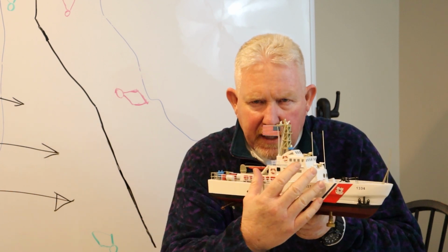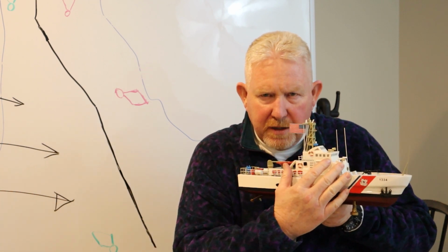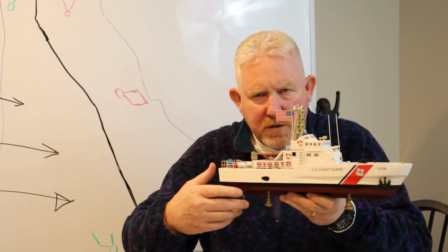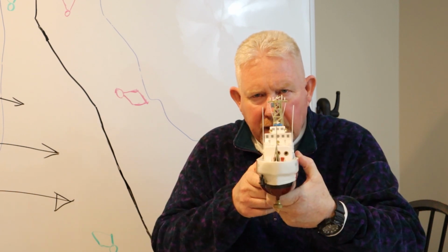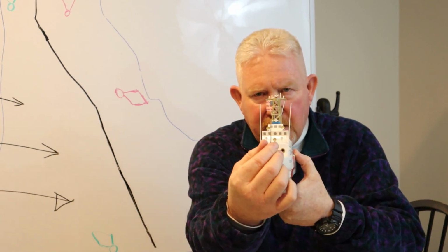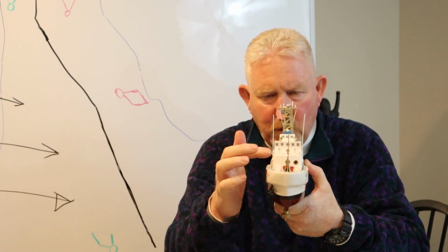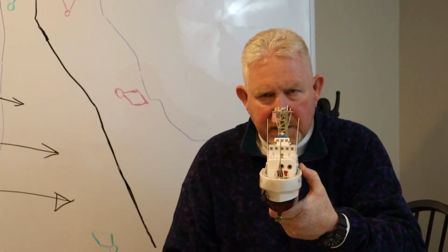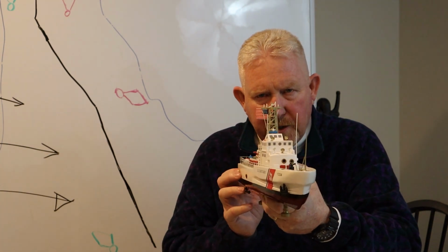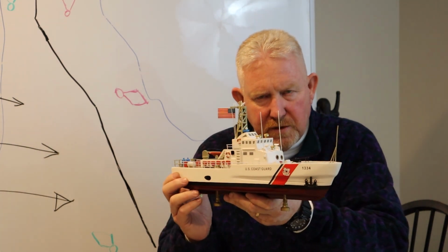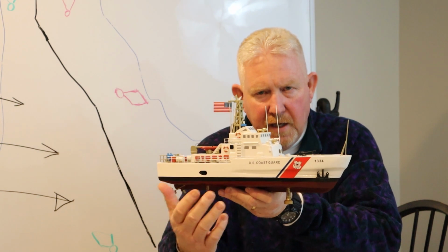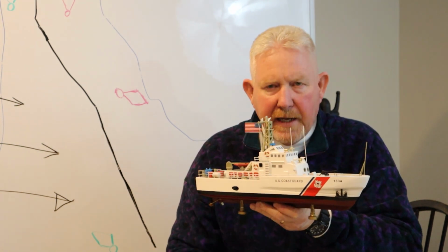The wind's coming in and it's blowing and it's pushing the boat. When you turn your bow into the wind, now the profile is coming from the pointy end here, and all your sail area is just this point and a little bit of the pilot house. As you turn yourself into the wind, it is able to push you back.